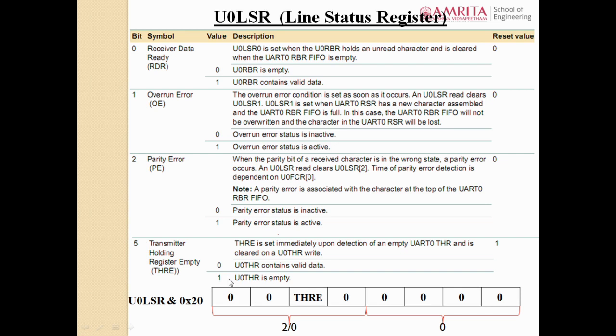Right. So for that I told before, if you want to check a particular bit, what you should do, you need to split that bit. How will you split a bit? You need to AND with that bit alone as 1, all the other bits as zeros. So all the other bits will be matched with 0 except this bit. So this bit should be 1, all the other bits 0.